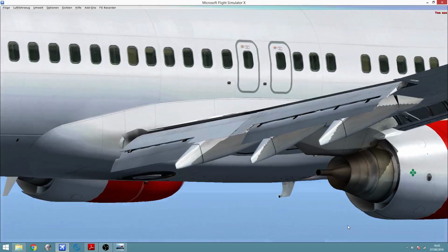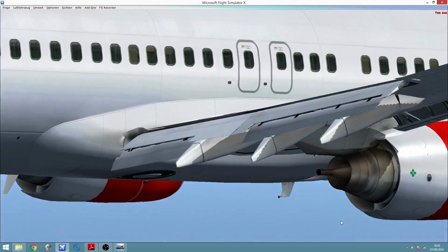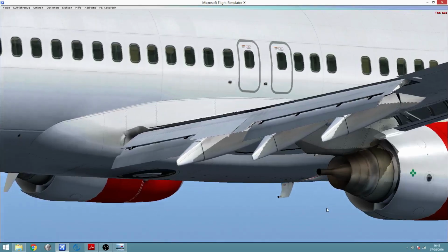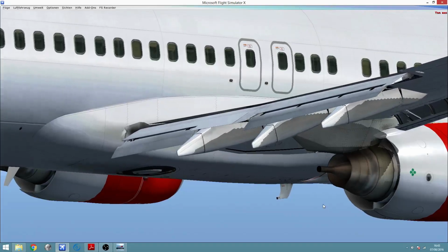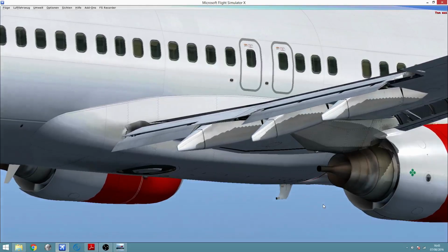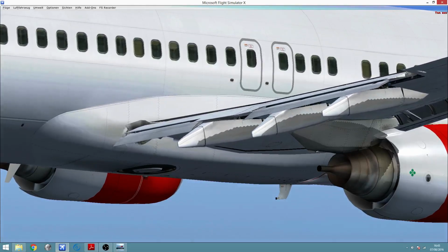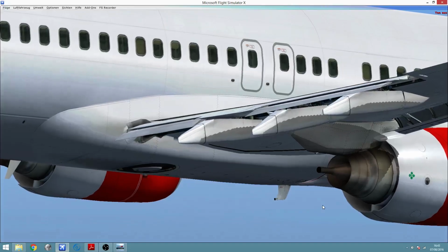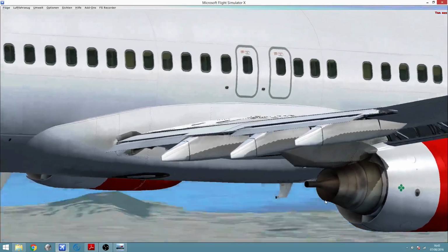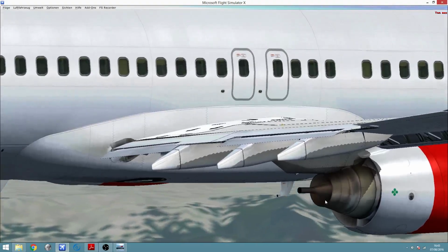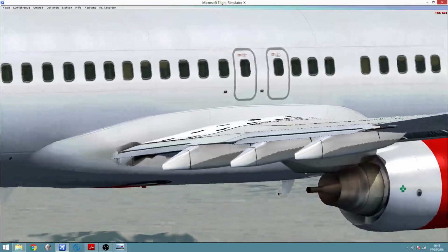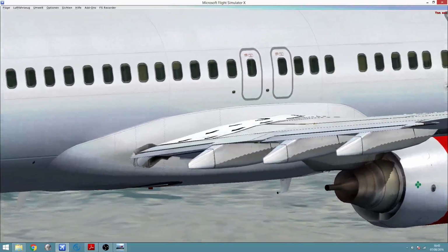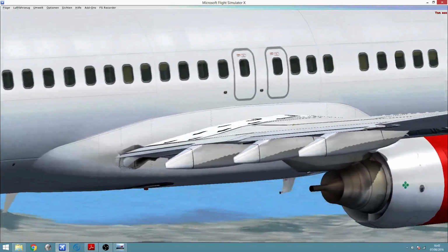If I wanted to retract the flaps, I would have to press F6 per point. All right. If I wanted to completely retract the flaps, I would press F5. If I pressed F5 only once, the aircraft would completely retract the flaps, and this is what we name a clean aircraft. An aircraft that has the landing gear up and no extended flaps is named a clean aircraft.